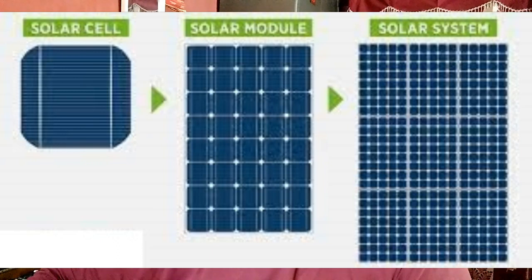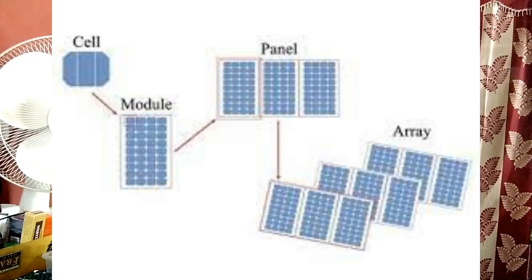And the next point is raw materials. The basic component of a solar cell is pure silicon. Pure silicon is derived from silicon dioxides such as quartzite, gravel, the purest silica, or crushed quartz. The silicon discs are shiny and require an anti-reflective coating, usually titanium dioxide.